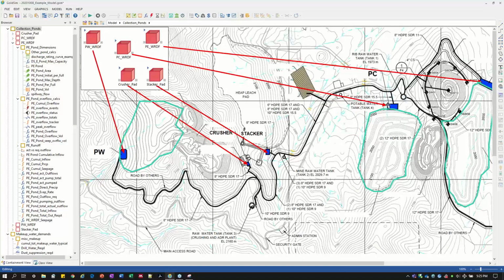And then the other big thing in terms of the ponds, that water is, depending again on the geochemistry, something that can't be allowed to discharge off site. This needs to be managed appropriately. So ideally, we're first using that water as much as possible in this process area, or there may be conditions, a storm event or a big snowmelt event in the case of where this site's located, where maybe there's competing needs, or maybe there's too much water and we have to send it to some sort of emergency pond.